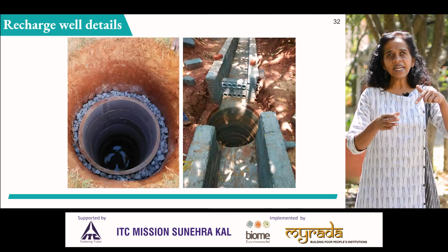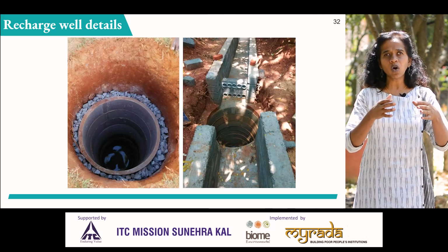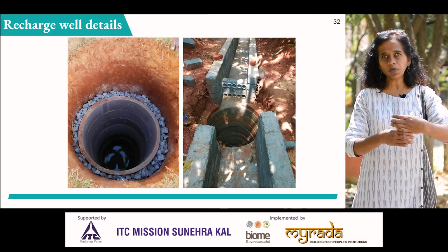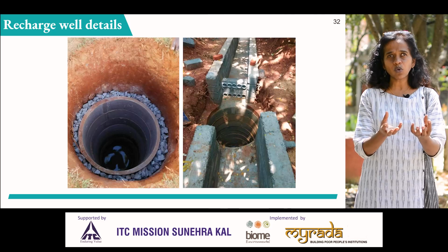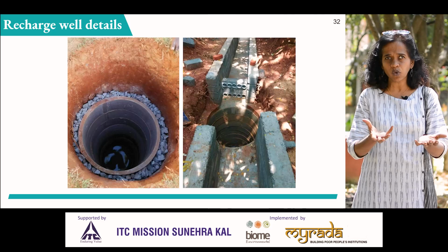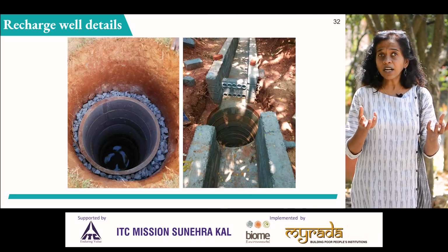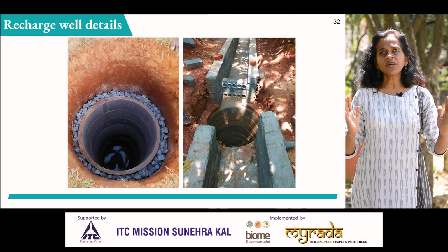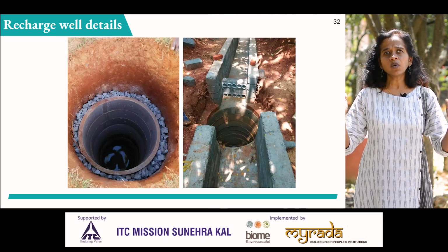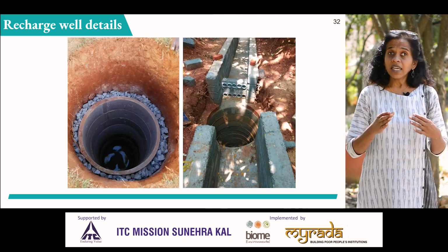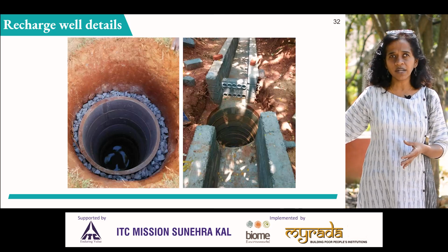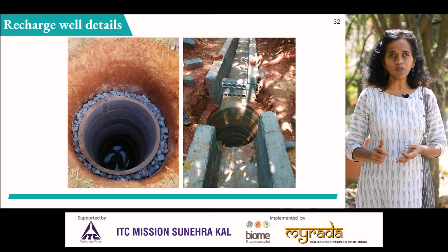The well then is lined with readily available concrete rings for structural stability. These rings are stacked up one on top of the other, and then you place jelly stones or big stones all around in the space between the rings and the soil. These stones are sterile, don't put any organic matter there. What you're trying to do is fill these gaps tightly so that the well does not collapse. Initially, it's good if these wells in a layout can be placed in storm water drains, because that's where most of the runoff happens.